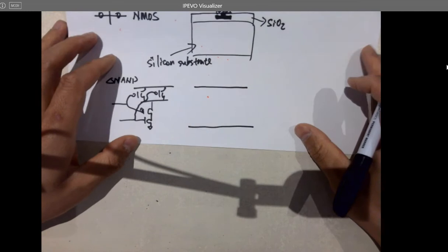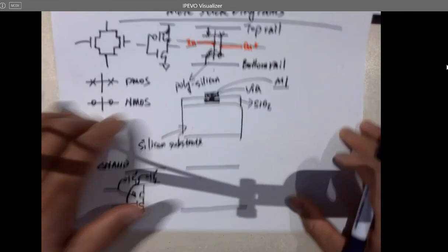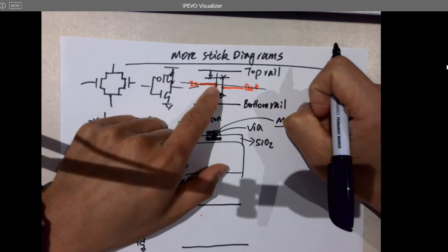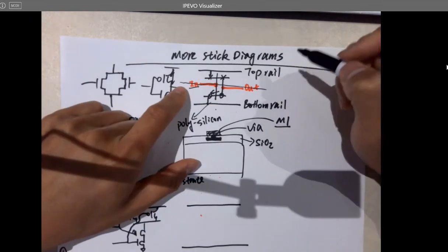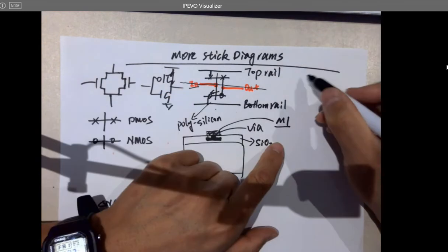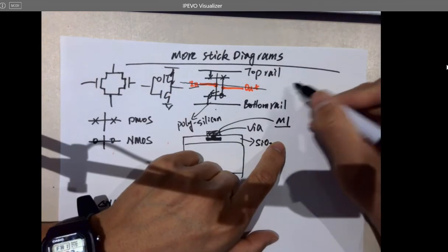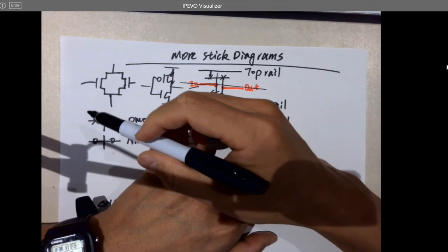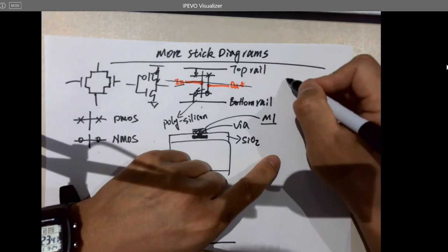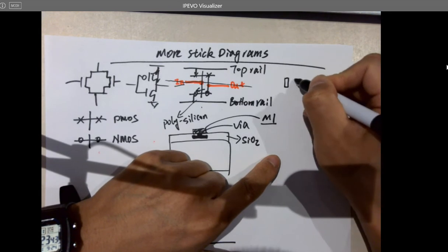But when you are drawing that stick diagram, the stick diagram here represents the layout, just keep in mind. Remember, I think, did you do that? Yeah, you did it on Tuesday this week, for the NMOS and PMOSes, right? So when you drag a PMOS or NMOS from the library in Electric VLSI, it looks something like this, right?